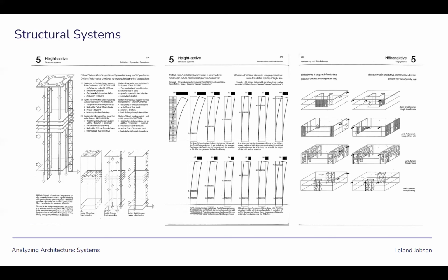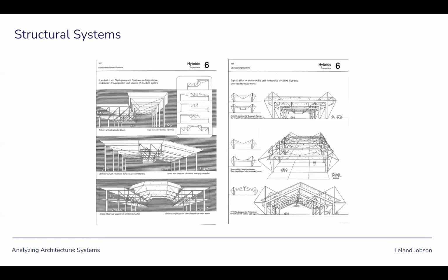So why is that? Well, then the whole structure is like a column, right? So the moment of inertia of the building, and if you're familiar with that, the distance from the center is a huge driver in how much capacity it has to resist bending. So you just move the structure further away from the center of the building and get better effect. That's what this is describing here, more or less. And hybrid is, you know what a hybrid is.